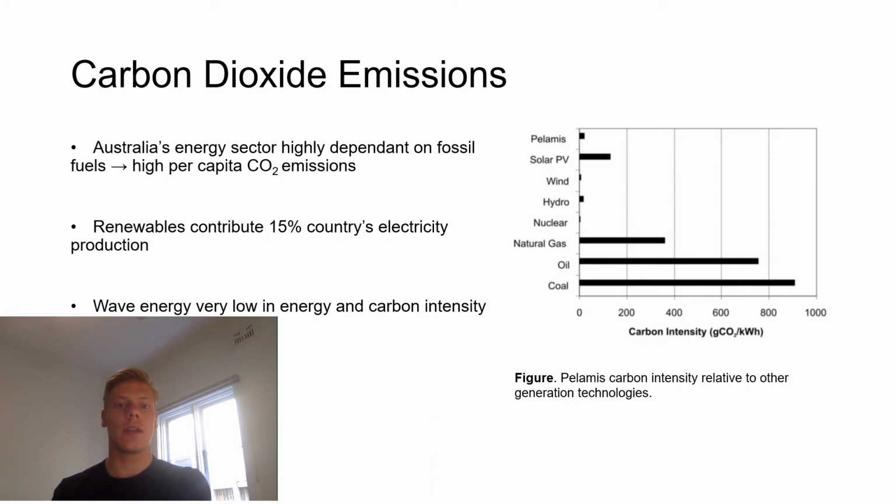At 293 kilojoules per kilowatt hour and 22.8 grams of CO2 per kilowatt hour, the respective energy and carbon intensities of wave energy converters are comparable with large wind turbines and very low relative to fossil fuel generation. Like wind turbines, the most significant environmental impact arises during manufacturing, material use, and shipping of the wave energy converters rather than through operation and maintenance.